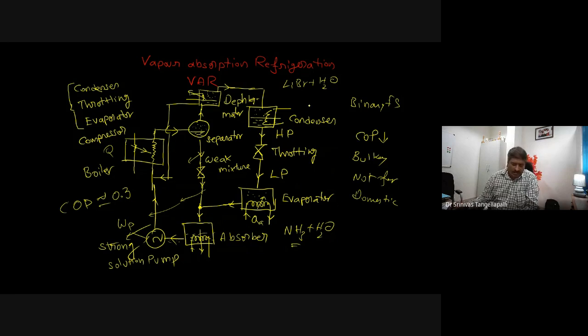In Gurgaon, I visited one solar cooling system, a solar energy center, long back. They have a triple effect lithium bromide H2O vapor absorption refrigerant system. The COP of the triple effect vapor absorption is 1.27.